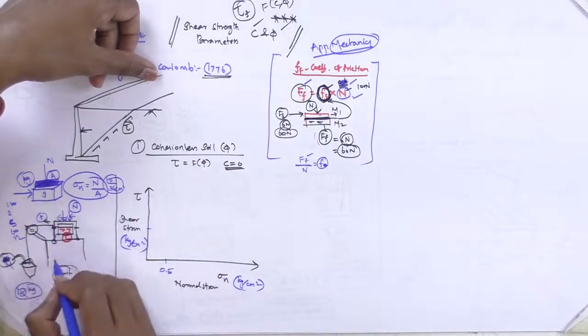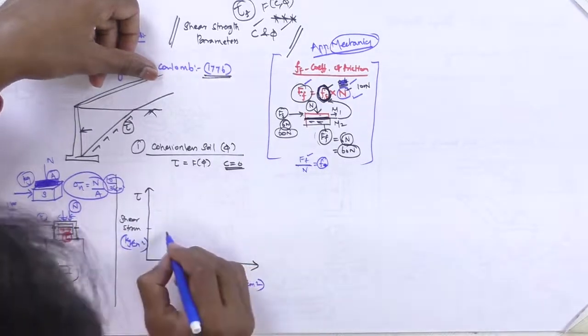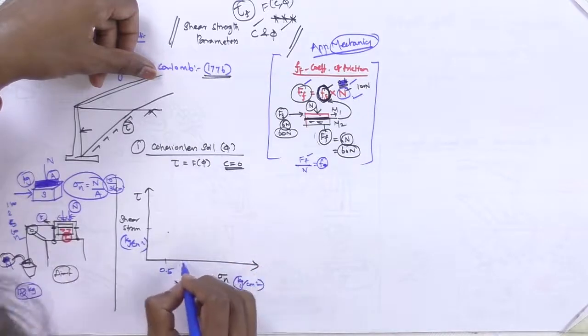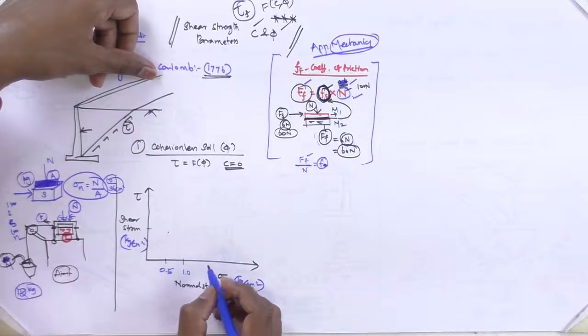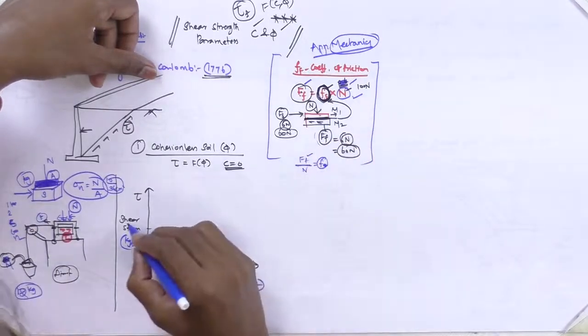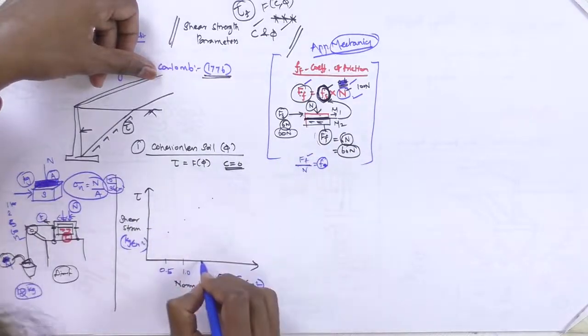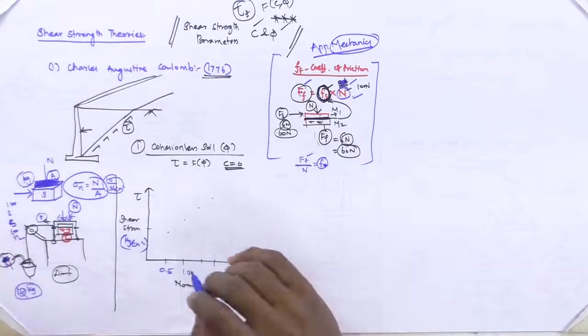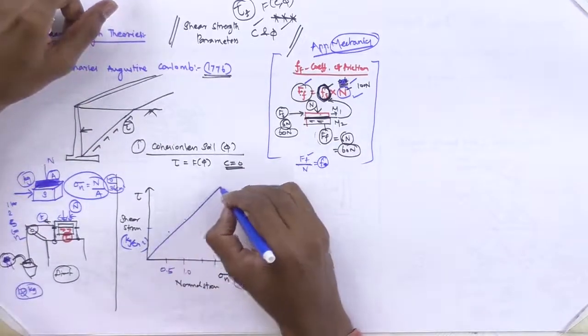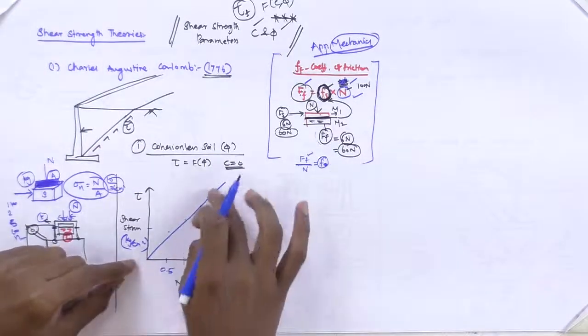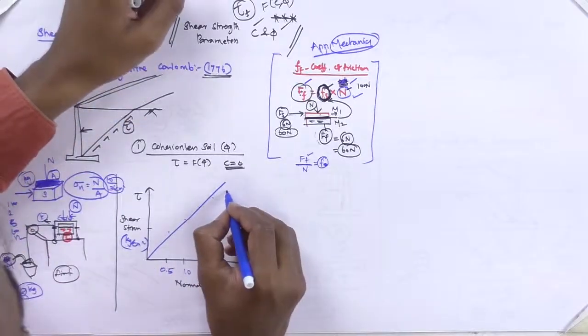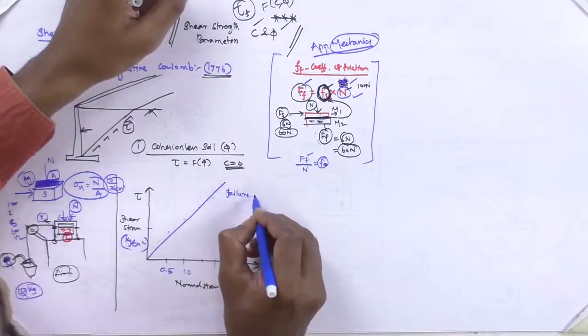So convert in terms of force by area, you get stress, so you get some point. By the way, increasing to 1 kg per cm square, the same thing, it fails at a different load as explained. So for different values we get points like this. Once you draw a line like this, this is what is called the failure envelope.